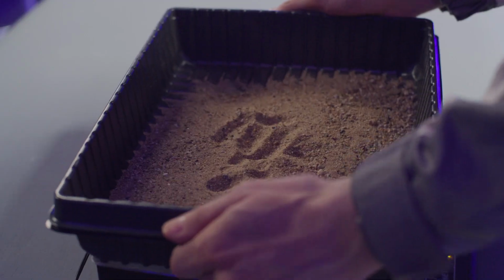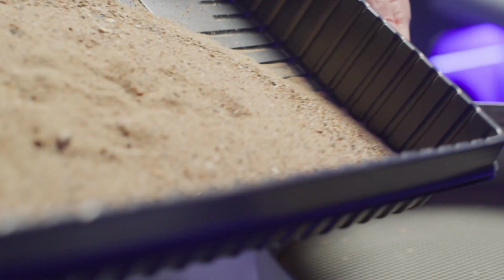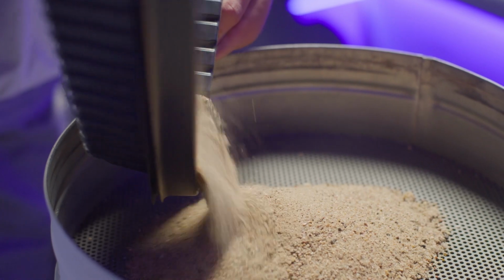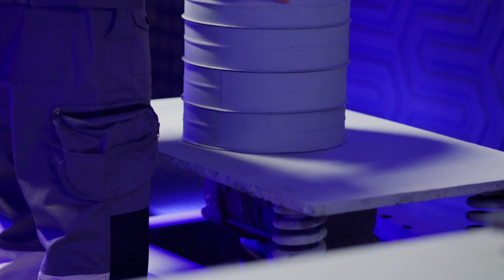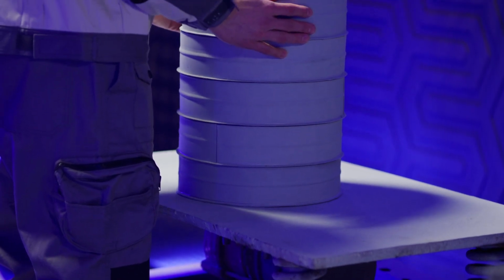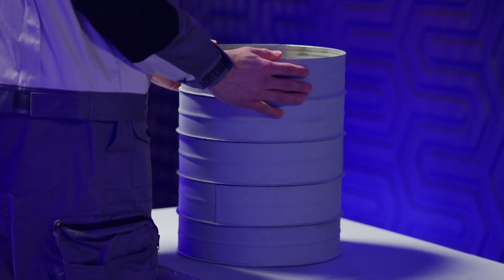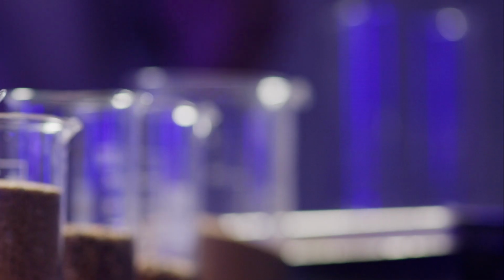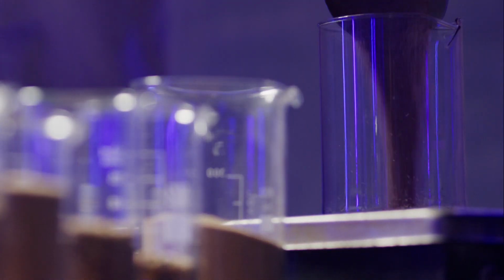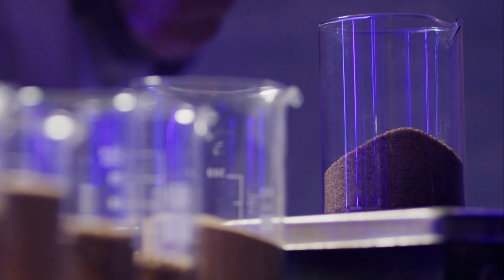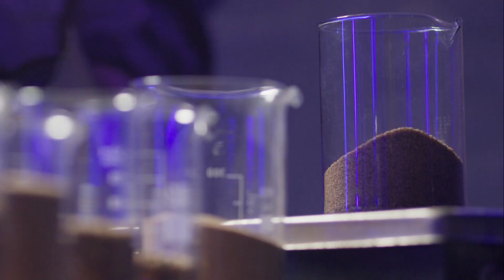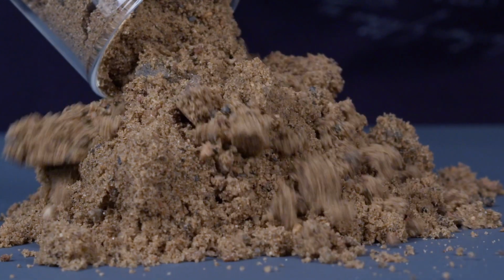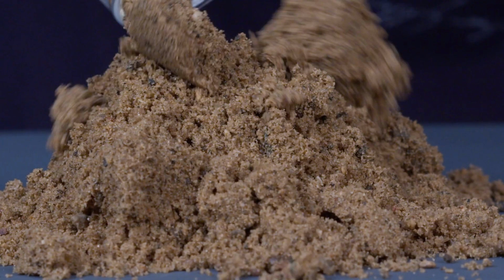Therefore, before the sand is put into production, it's important to find out the particle size distribution of a particular batch. How is it found out? Another subsample is taken and passed through a series of special laboratory sieves. The sand passes through screens with different meshes, and grains of sand of a certain size are retained in each of them. So the entire volume of sand is divided into fractions. Then the mass of each fraction is measured, and with this in mind, the fineness modulus of sand is calculated.